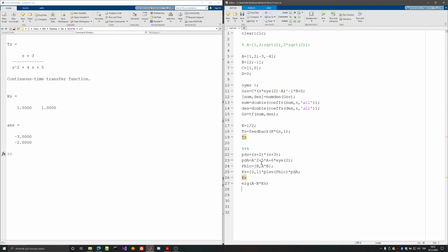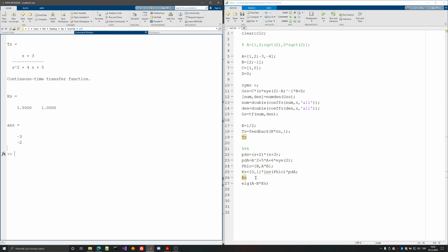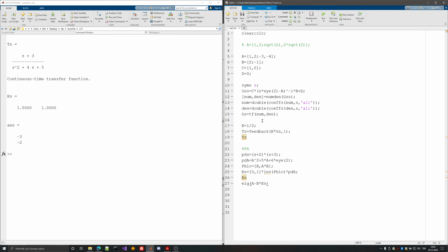But as I've told you, even though it seems like if you use P inverse, it should be the case, but it is not. You are not able to assign the poles. You have to reduce your system, and then you should go ahead and design your state feedback controller, because the feedback controller needs all the states in order to take the linear combination to construct your feedback.